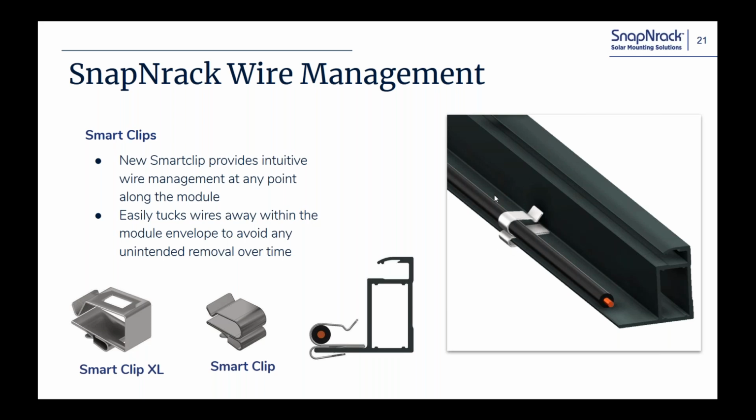And that's typically where you want all your PV wires, up inside this module frame right here. That keeps it off the roof. It keeps it secure from anything that might happen to it over the 20-year lifespan of the system.